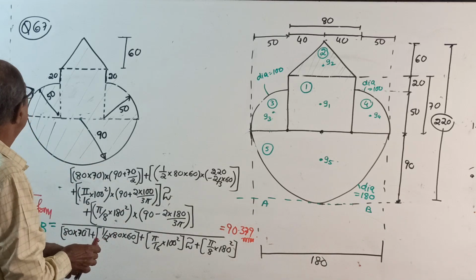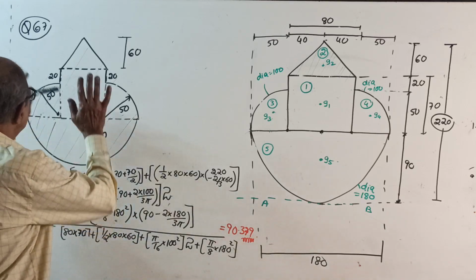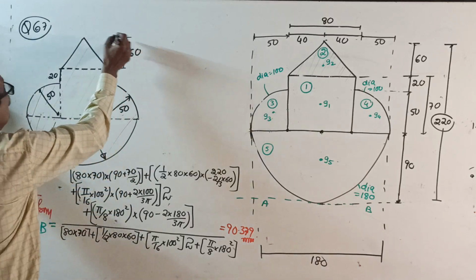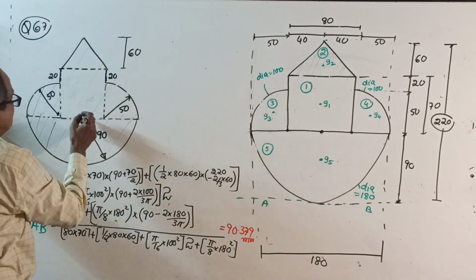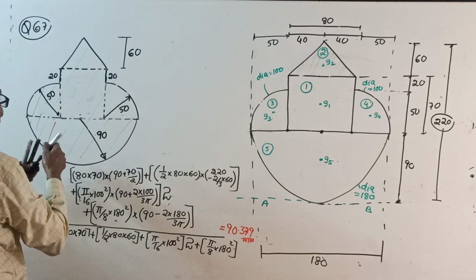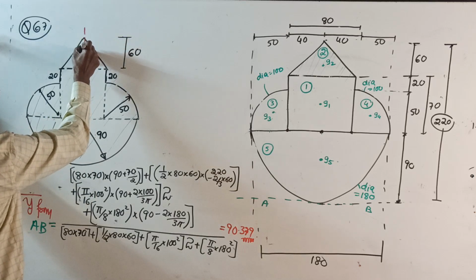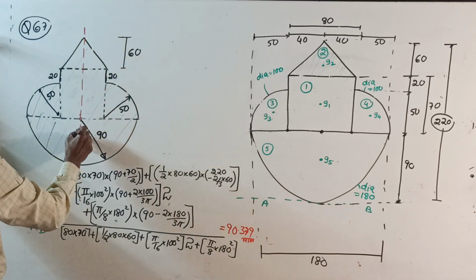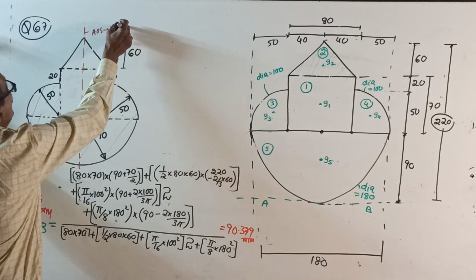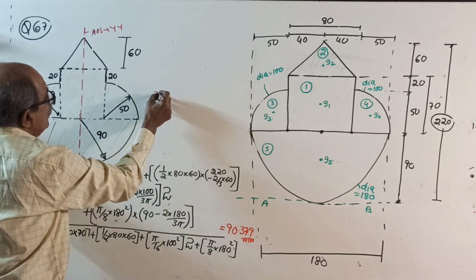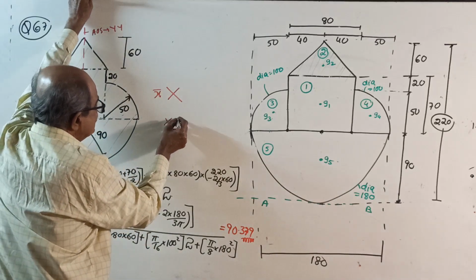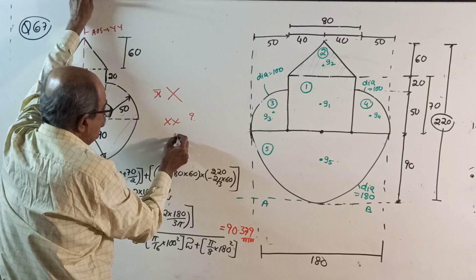Now, first, make a note. How will you first put the sketch? See, first try the sketch. Then do one thing. Once again copy the sketch. Then first write. This is perfectly symmetrical about YY. See, this is axis of symmetry. That is your YY. Therefore, right here, no need of finding X bar. Okay. So only XX to be located, so you require Y bar.